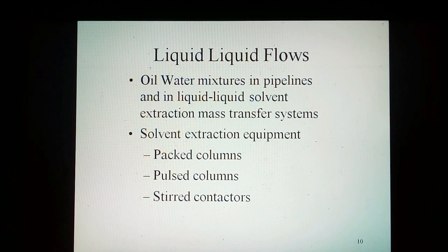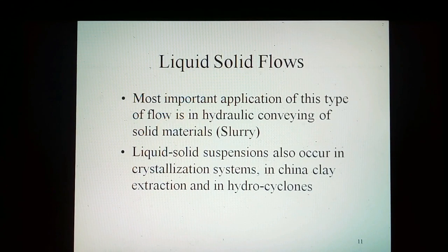Liquid-liquid flows. Examples of the application of this kind of flow are the flow of oil-water mixtures in pipelines and in liquid-liquid solvent extraction mass transfer systems. Solvent extraction equipment includes packed columns, pulsed columns, stirred contactors, and pipeline contactors. Liquid-solid flows. The most important application of this type of flow is in the hydraulic conveying of solid materials. Liquid-solid suspensions also occur in crystallization systems, in china clay extraction, and in hydrocyclones.